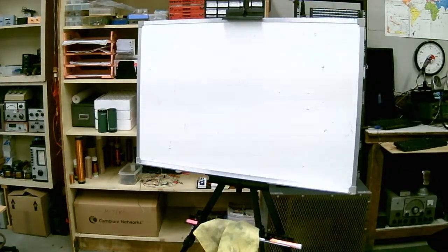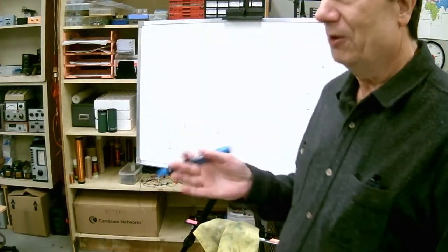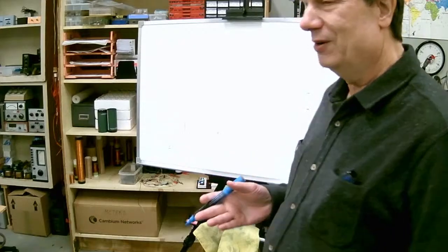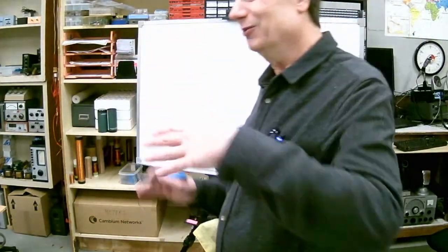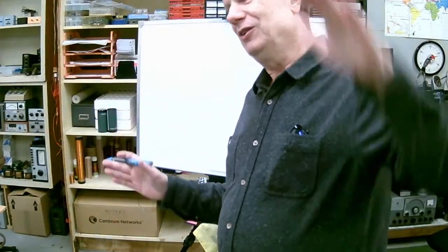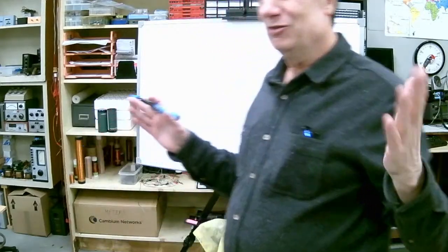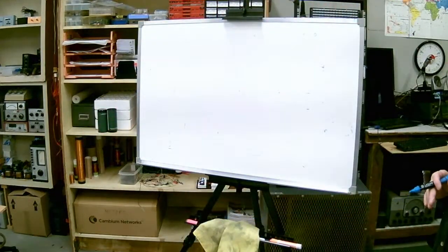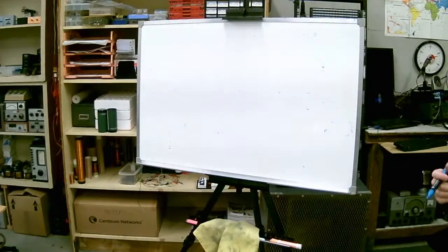The field intensity is a voltage per linear unit. There are a couple of other ways of measuring that when you get into microwave. It can be practical to measure the actual surface area of the antenna, like with a parabolic dish, which has gain in both vertical and horizontal even though its polarization is only in one direction. There are also half parabolas, which are parabolic in just one dimension and are a little easier to calculate.